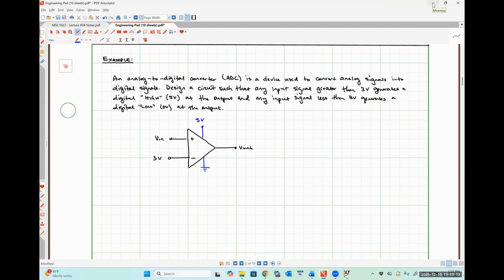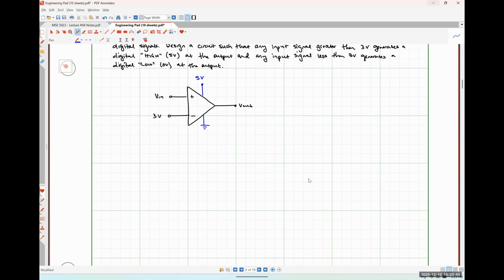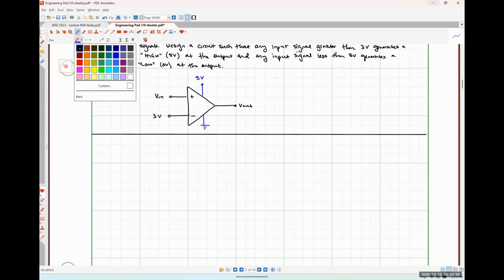So what kind of circuits do we know about that allows us to take some known voltage and shrink it down to some smaller voltage? Voltage divider. A voltage divider, okay? So we are going to use a voltage divider network in order to establish a resistor biasing network. So let me hide this. I'm going to call this subsection here resistor biasing to establish VREF.